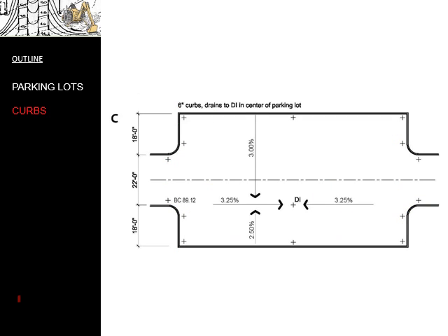In the third example, we basically have the same idea set up for you with the addition of a drain inlet in the middle. A drain inlet in the middle means that all of the slopes are going towards that drain inlet. And that's an important concept when you start to figure out where the contours are going to run.